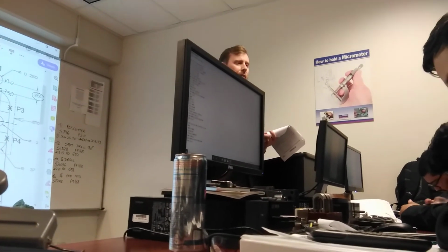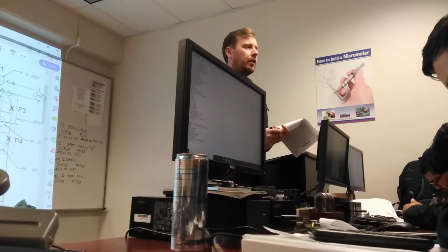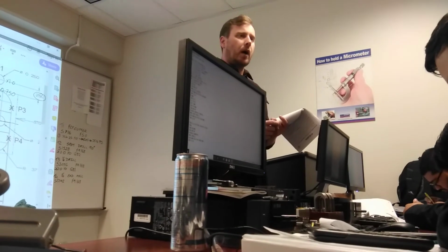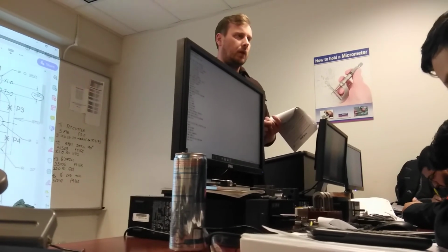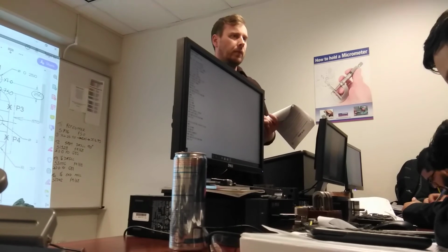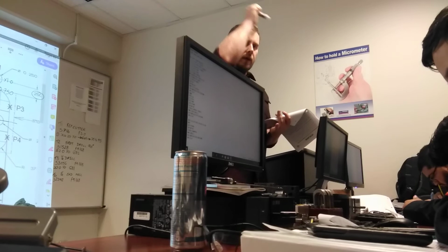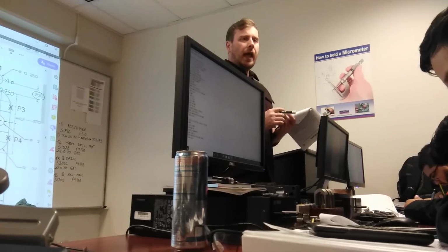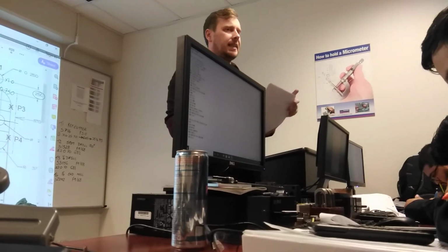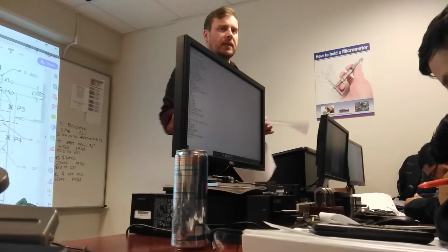Otherwise, the machine's going to compensate how much? Nothing. You're going to scrap your part. So always move to a clearance position, always bring the Z down, and always program a D. D for diameter.